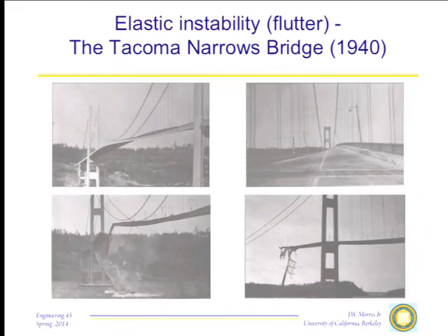But remember that if you have a vibrational mode that's going to pick up some obscure vibrational mode and destroy an engine or some other piece, then that's a combination of two things. It's a natural frequency of your assembly, and it's also your power plant is somehow producing that frequency too. So the two things have to kind of match together. So the chance that you will move the natural frequency to some other frequency that the power plant is producing is not very high. If you can find out where your problems are, they're usually not that difficult to solve.